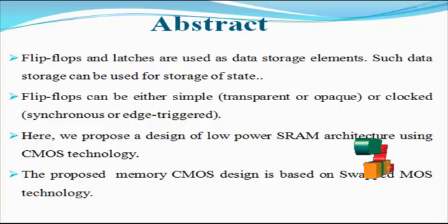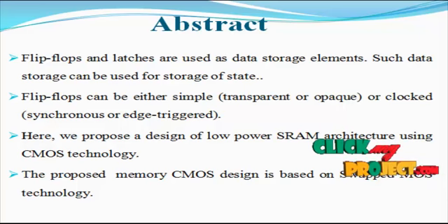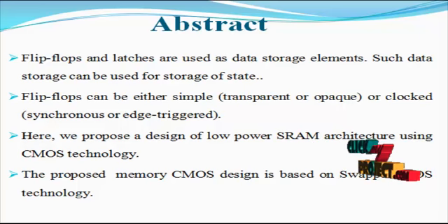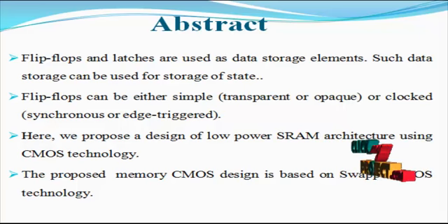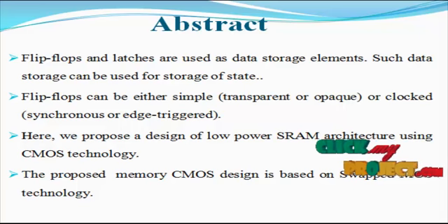The most commonly used SRAM type is the 6T SRAM, which offers better electronic performance in all aspects: speed, noise immunity, and standby current. The smallest 6T SRAM cell fabricated to date has an area of 0.08 micrometer square and was fabricated in 20 nanometer technology based on our proposed designs.